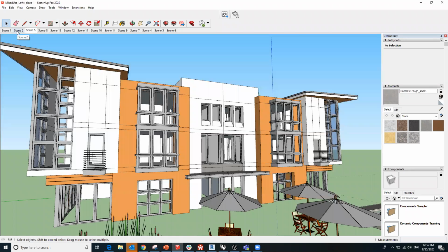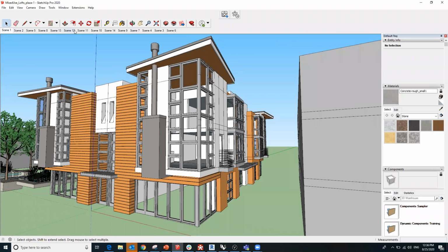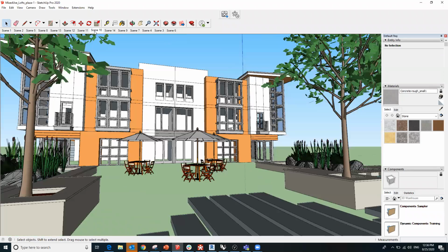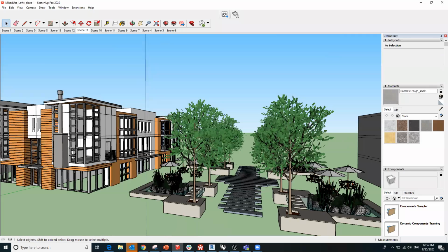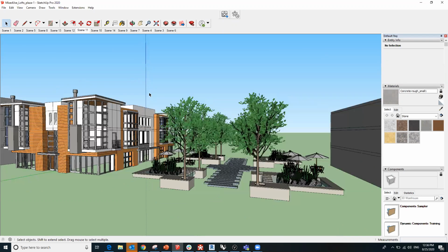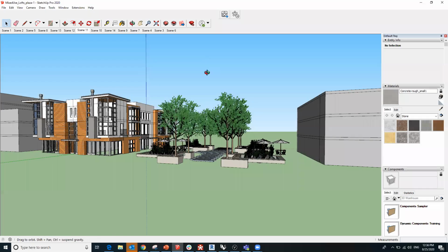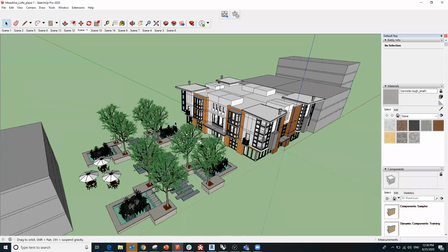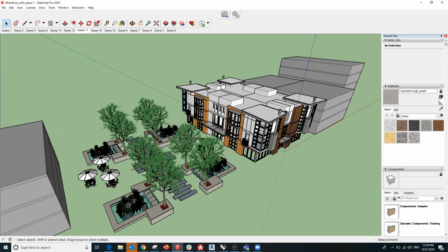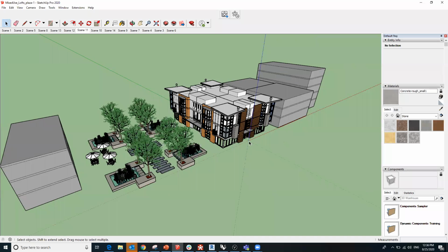So if I look up here, or excuse me, scenes, they're called. I have certain scenes set up in my SketchUp project. These are related to a certain camera point, but also where the building sits. So the point being, if I move this entire model, I pretty much have to recreate all these scenes that I just formatted here in this model. So again, I think it creates extra work if you're going to move the entire model in relation to this point and bring it into Revizto.